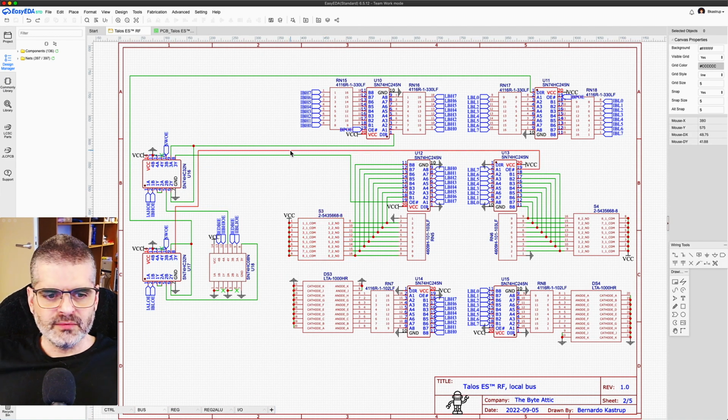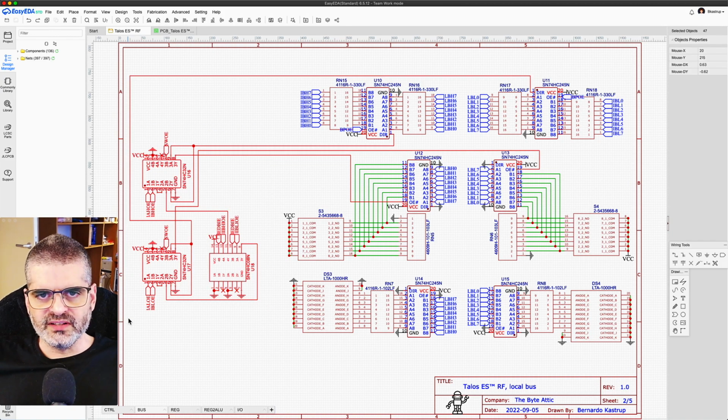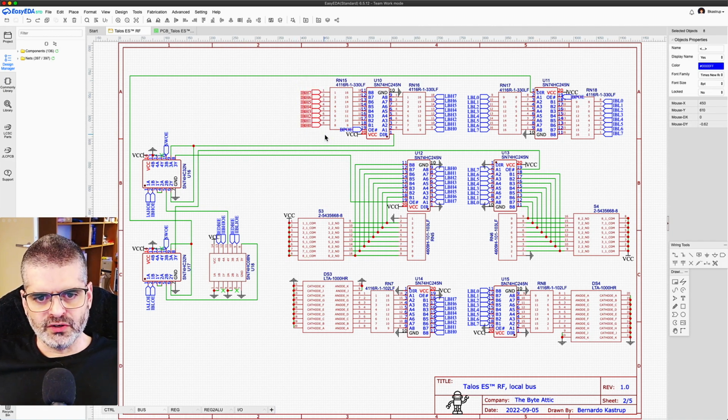Then the bus themselves. These three ICs are the control logic that we discussed in the simulation, and they feed the directions and the output enables of some of the buffers here. These are the signals of the internal bus high as they come through the backplane connector.